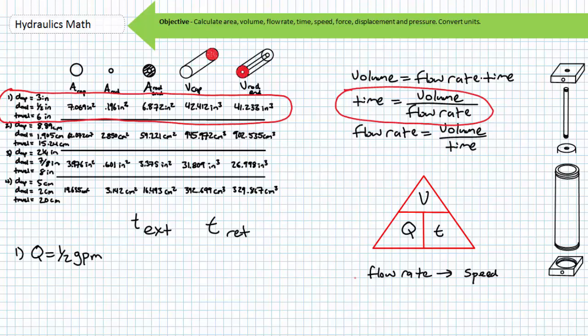The act of retracting a cylinder means one is filling the rod end, not the cap end, the cylinder with the rod volume removed, or the tubular volume. Stay organized. Use a diagram with all the terms and formulas attached. Visualize the act of extension and how it differs from retraction.